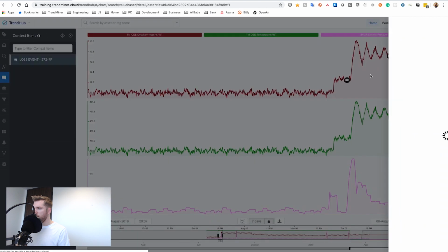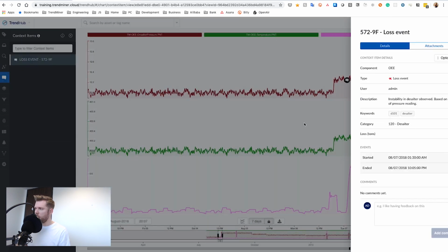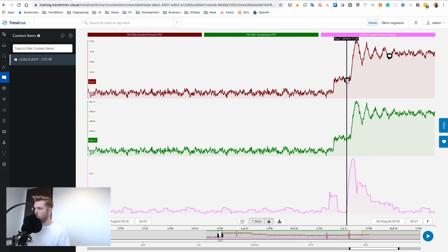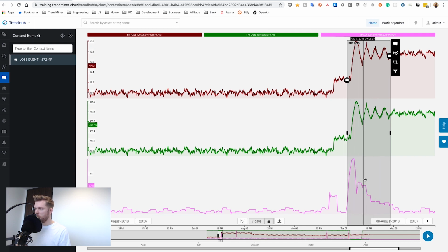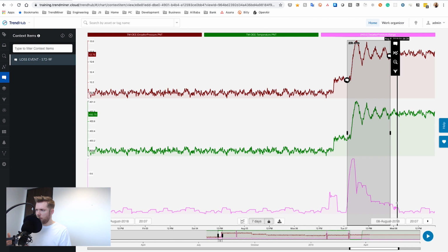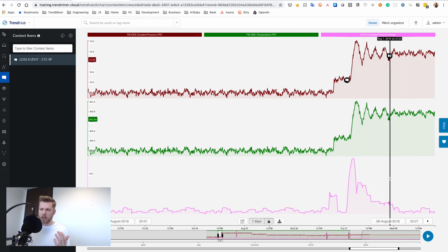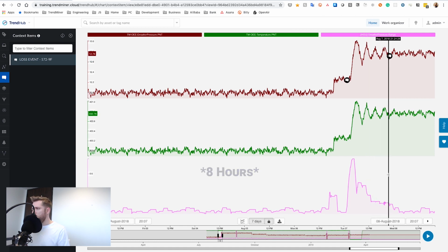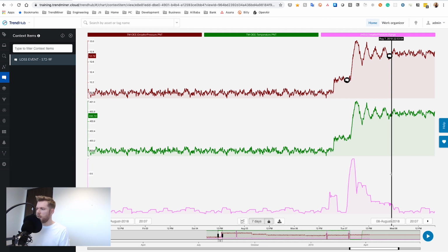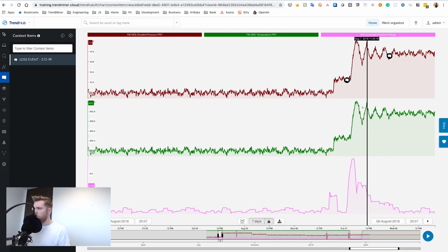And again, you see these annotations popping up. The ones I had just created are now added to my view. You notice that it spans around this period where I go through some kind of change, some oscillations, and it takes a while for the stability in the desalter to return. But at a given point, I get below the limit of 0.2. I stay below that limit for a significant amount of time, which I think we had set up as 10 minutes. Or no, we increased that value, sorry. But that's how you see how those search conditions can affect the way you create your results.